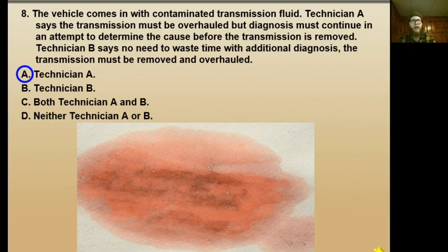And oftentimes, if you just pull a transmission out and replace the parts, you'll find that something broke or a seal is bad, and that could very possibly be the root cause. But if it's a control issue, like a harness is damaged, maybe got melted on the exhaust, or a solenoid or a valve in the valve body isn't actuating properly, then we could do this overhaul and hopefully catch it on our test drive before too much bad stuff happened.